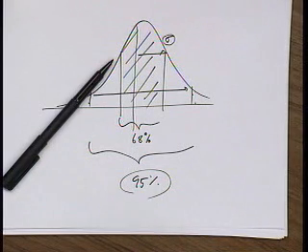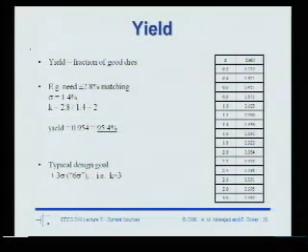So customers have to test a lot of parts before they find one that doesn't meet spec. Usually when someone tells you the offset voltage is 10 millivolts, you can call them up and ask, but it probably means 6 sigma or plus minus 3 sigma. So you've got to try really hard to find an op-amp that has more than 10 millivolts of offset voltage.